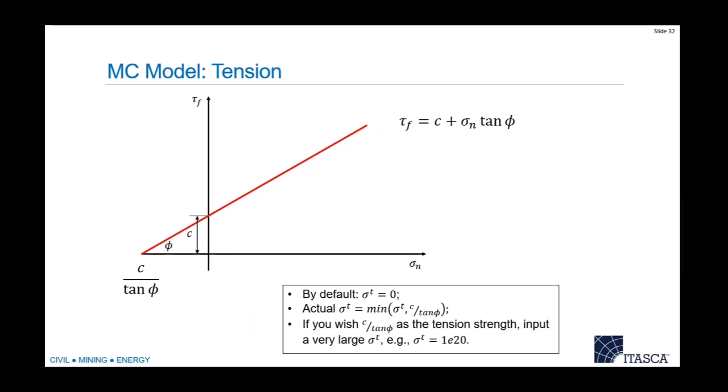And for Mohr-Coulomb, no big deal. But you can imagine these more complicated ones where they have strain softening or some other wacky behavior. Following along that line explicitly is actually pretty efficient, whereas trying to figure out how to do these corrections and come back to some wacky line is much more challenging. So this is kind of the reason that, 25 years ago, they decided to go for the explicit approach, because they assumed that we would be doing complicated nonlinear things. And it's easier to follow those paths with the explicit approach. And implicitly, it's more challenging. I mean, it's certainly possible because these other programs have these models in them, but it certainly becomes more difficult.